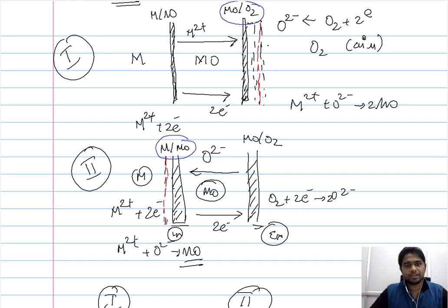So this is one aspect that you need to understand when you are differentiating the two mechanisms of oxidation. In the first mechanism, which is characterized by the propagation of the metal ion and the building up of the oxide layers at the external interface, it is possible that the newly formed layers are removed. Therefore, the MO more or less remains constant. It appears as though the metal consumption has stopped. However, that might not be the case. So this is one interesting aspect of mechanism 1 when compared to mechanism 2.